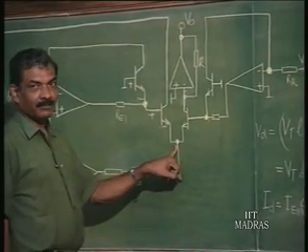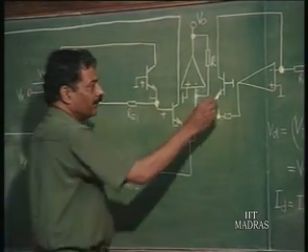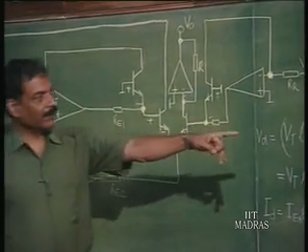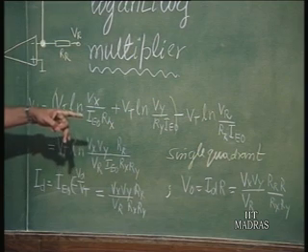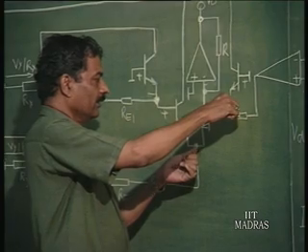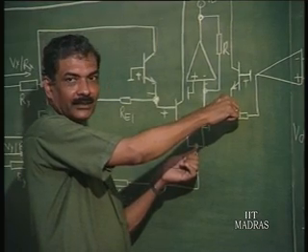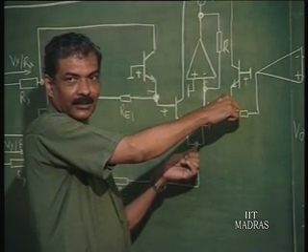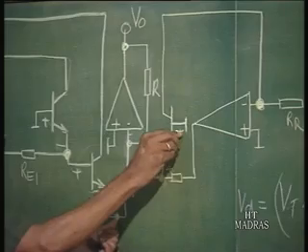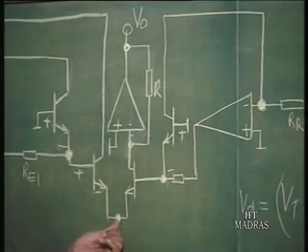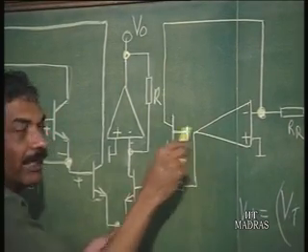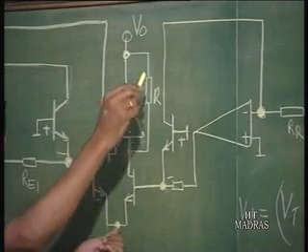Then I had to subtract from this another voltage, which is minus Vt log Vr by Rr IE naught. I had to subtract, or what I can do is arrange for these two voltages to be the difference voltages, both negative, and apply that as the diode voltage. So, this also I generate with respect to ground. What is the voltage that we want to generate? Corresponding to minus Vt log Vr by Rr IE naught.